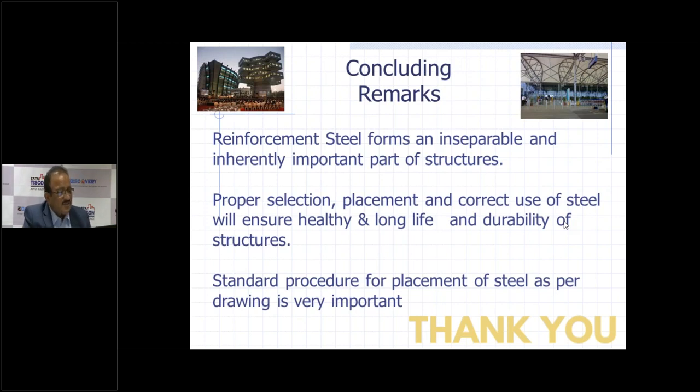So the significance is that before the steel bars are used at the site, they are tested for this bending, and they should not crack during the bending, and should not fail in a brittle manner. So that is why it is done.